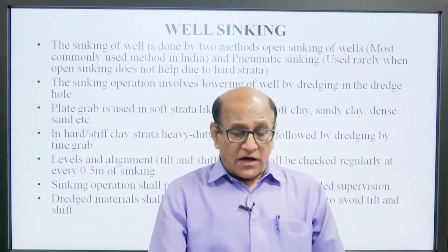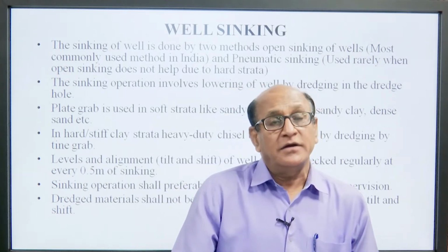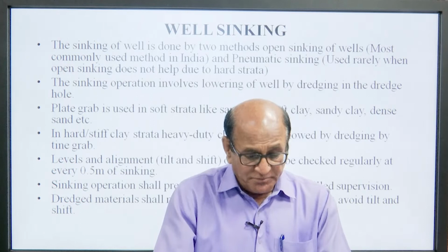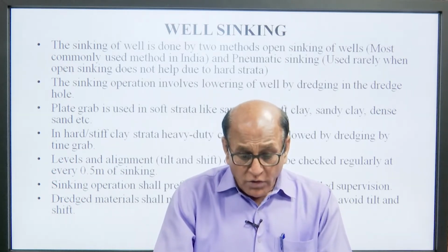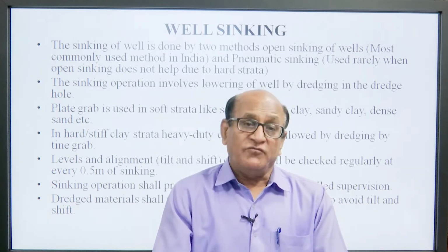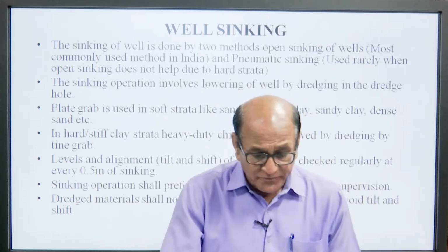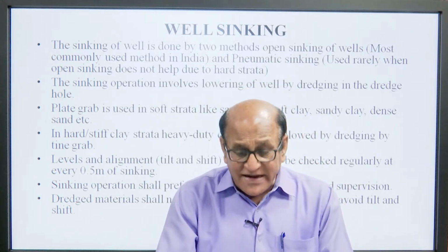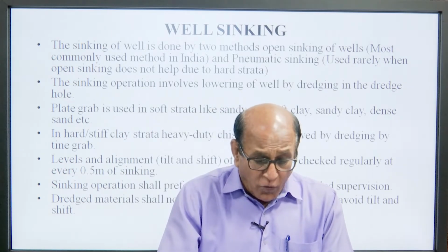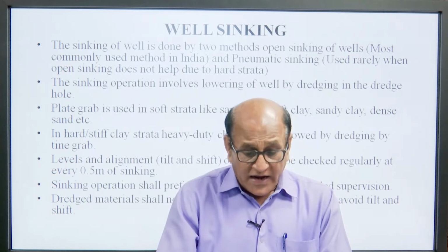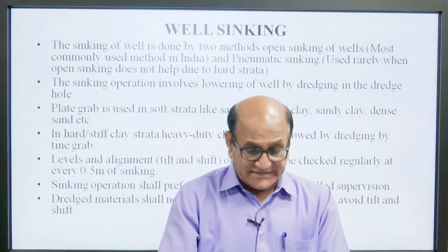Well sinking is another main important operation. The sinking of well is done by two methods: open sinking of well, which is generally used in India, and pneumatic sinking, used rarely when open sinking does not help due to hard strata.